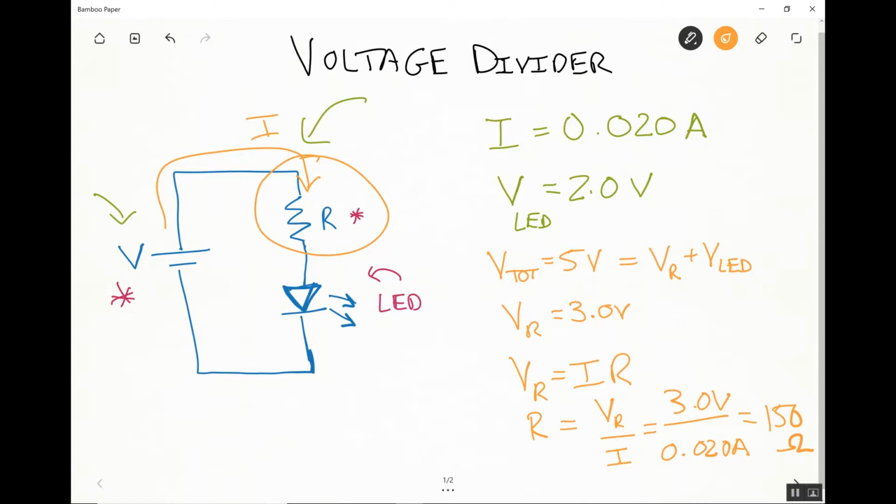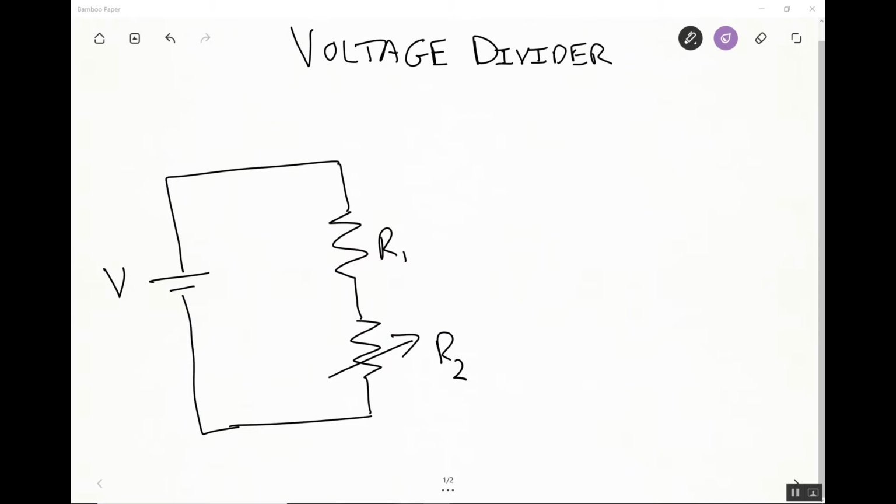So to just recap here, we have an LED. It's a green LED. We look at its data sheet. It tells us that this LED requires 2 volts and a current of 20 milliamps. We know we're going to hook it up to an Arduino Uno digital input-output pin that supplies 5 volts. If we just hook the LED up to the digital input-output pin, and that's it, the LED would burn out quickly because it's getting too much voltage, too much energy.